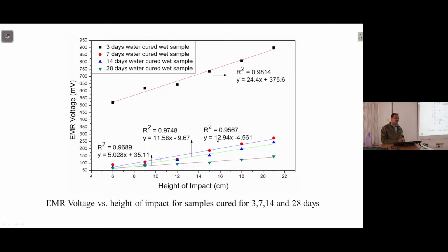So all in all, the point is the reaction is slow. So it takes time. Initially, this part, if we consider, here hydration is to a very small extent. It does not attain the strength. Everyone might have seen, when a structure with cement is built, you keep curing it for a pretty long time.